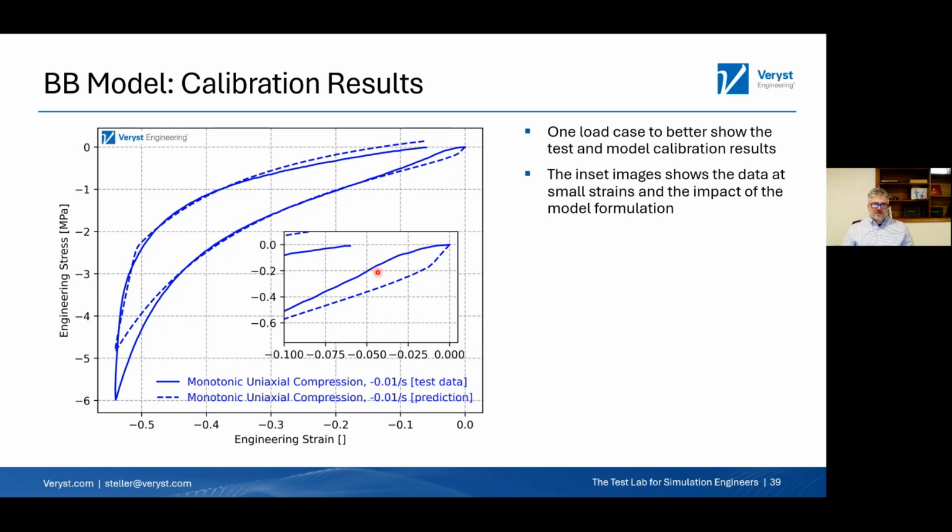That has to do with the form here. I like to call this a viscoplastic model, even though it's referred to as viscoelasticity, because essentially this is some yield-like behavior right here, and some of it can be permanent. So you need to be careful about that. That's kind of a downside to the model, but other than what's happening there at those very small strains, it's capturing this response very well. Not quite stiff enough here, getting the unloading shape very well.